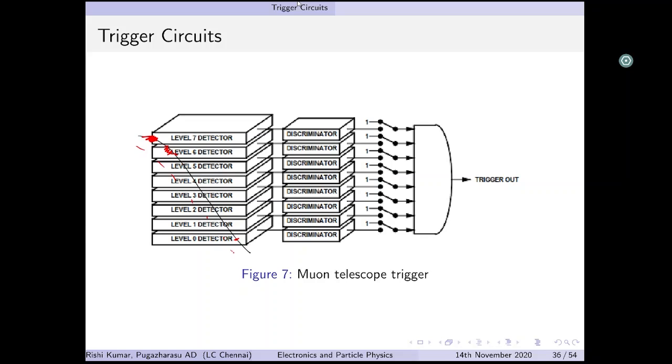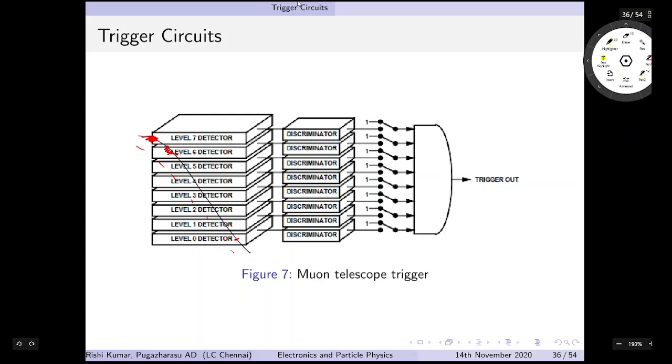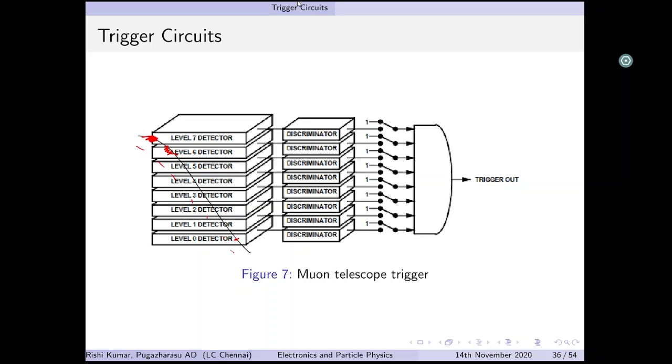And from a digital electronics perspective, how do I determine the intensity? If I was looking at the trigger output for a single event, it would basically be an AND operation. So if I'm looking at the AND operation, I want to know if the AND operation here on average was more ones or more zeros. Which one's larger on average? And when you compare that, you get that.